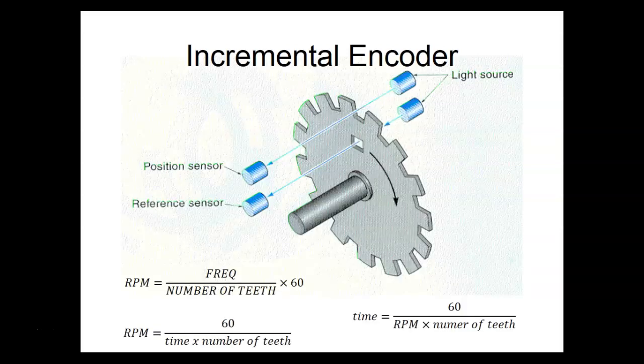So we looked at this already, right? Now what we need to do is be able to take, let me turn off my motor. Okay. We're going to have to be able to take the rate of the pulses and convert them into a speed. So we're going to have to figure out a transfer function.